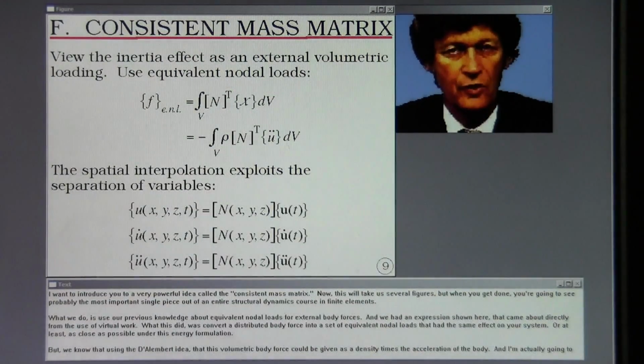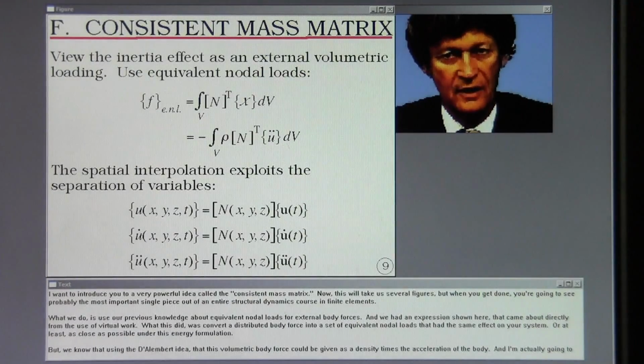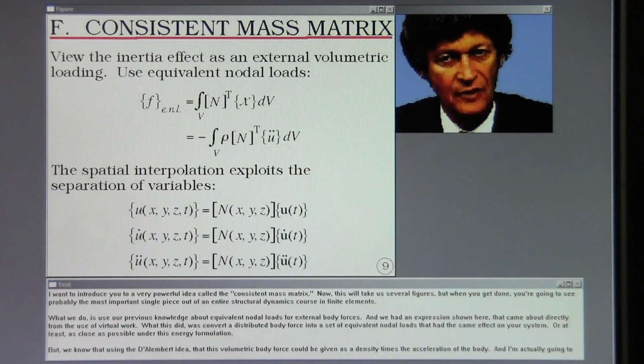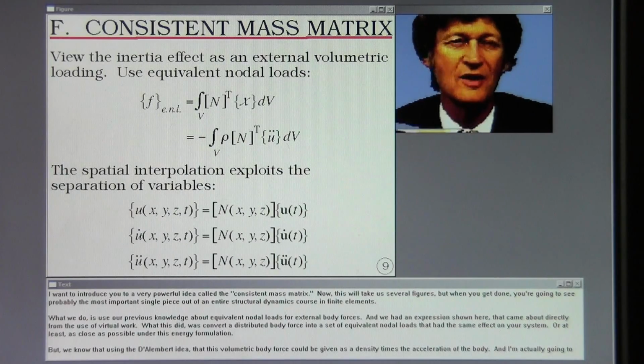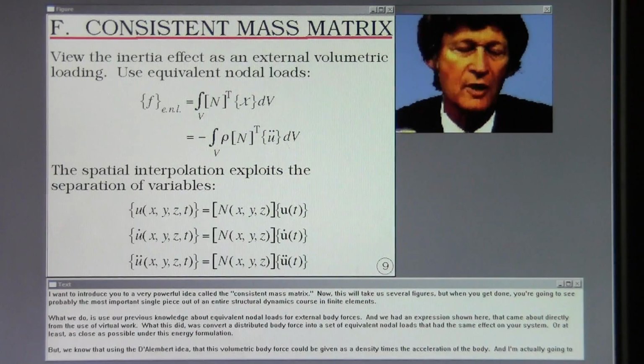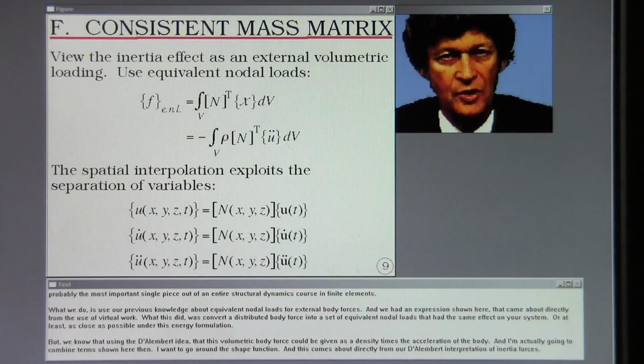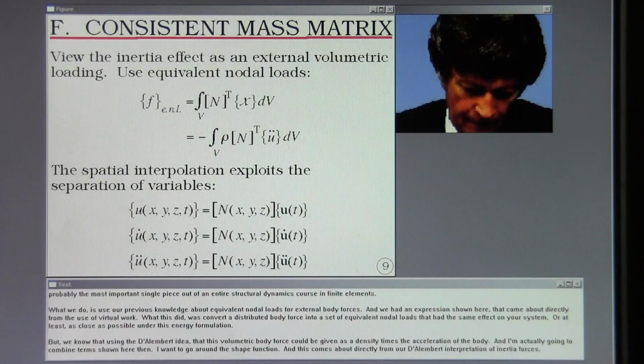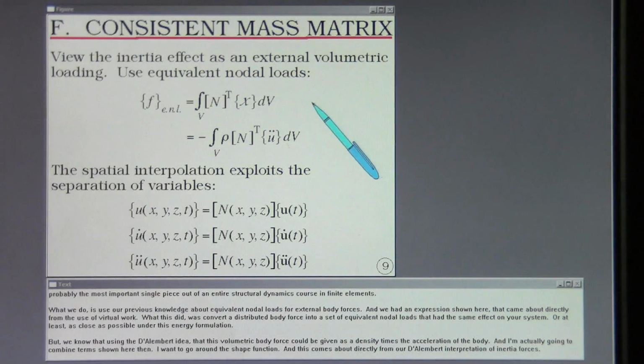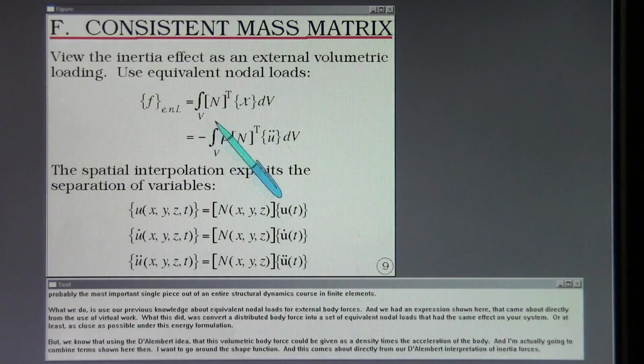I want to introduce you to a very powerful idea called the consistent mass matrix. Now, this will take us several figures, but when you get done, you're going to see probably the most important single piece out of an entire structural dynamics course in finite elements. What we do is use our previous knowledge about equivalent nodal loads for external body forces.